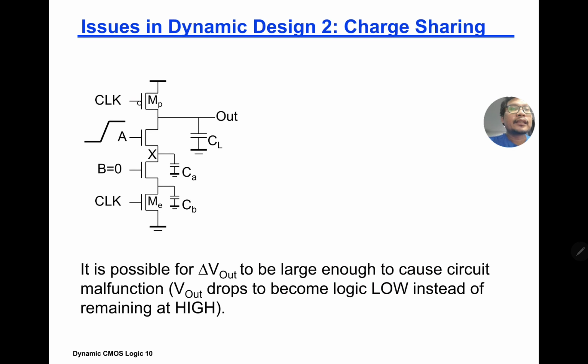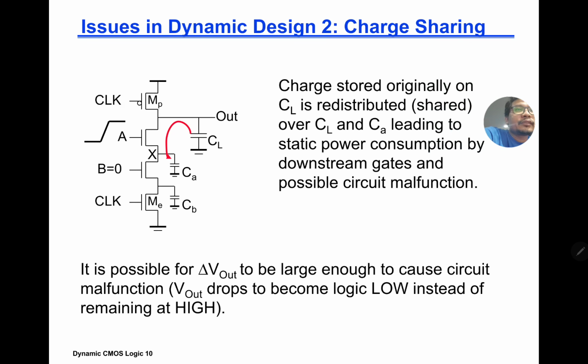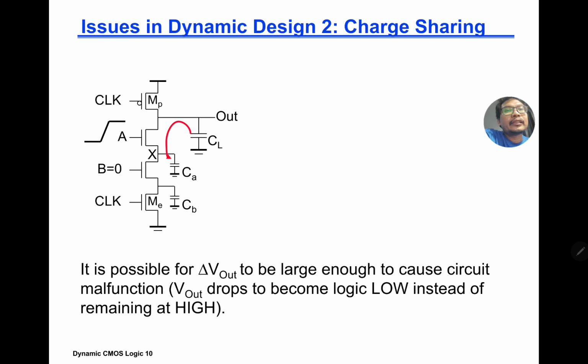Okay, issue number 2 is charge sharing. In charge sharing, it is possible for delta V out to be large enough to cause circuit malfunction. V out drops to become logic low instead of remaining at high. So this is another issue. During pre-charge it's okay.